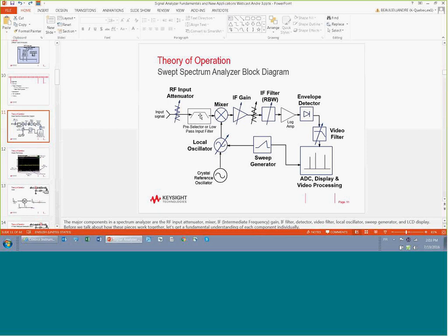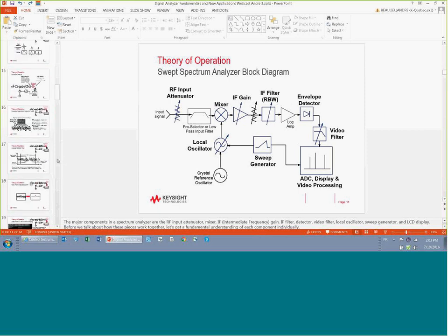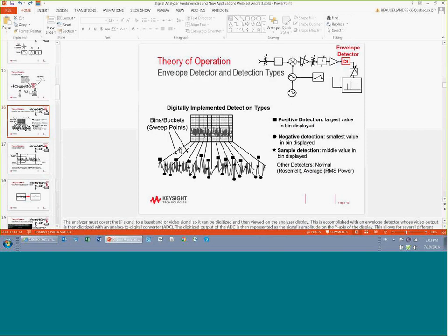If it moves, it was coming from the analyzer. If it's when you move the attenuator, it's coming from your signal. Okay. That the spectrum analyzer always captures its full range of points, which I think is 40,001, and then just displays the number of points these are selected. Right. It shows more than that.